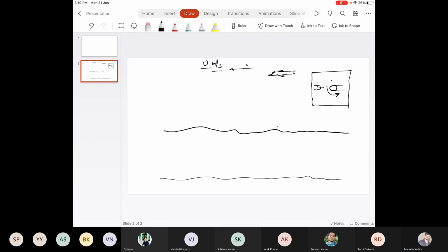Okay. So this mirror rotates this way. If you see this architecture of how the mirror rotates in the vertical direction, that rotation mechanism restricts the firing, the confinement of the laser beams, which are fired downward within a particular angle theta. And this theta is called FOV, field of view. Okay, we'll see the role of theta.